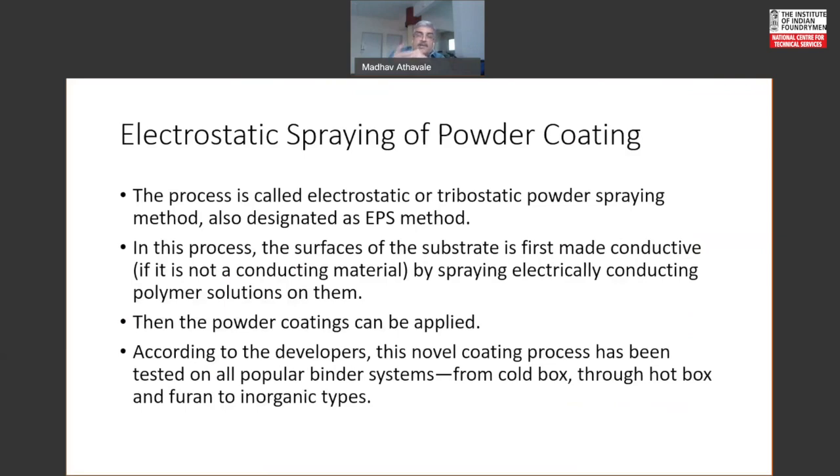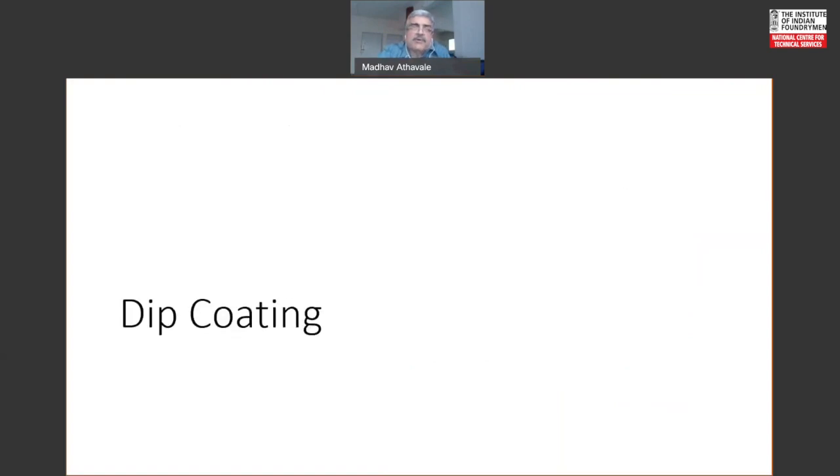Now, the application that we had chosen was a high pressure molding line making engine block casting. And as I said earlier, it is very common to spray a spirit-based coating to get good surface finish by avoiding metal penetration in those cases. And we had tried this. It did work okay in trials. However, for regular usage, it calls for a very high level of automation.